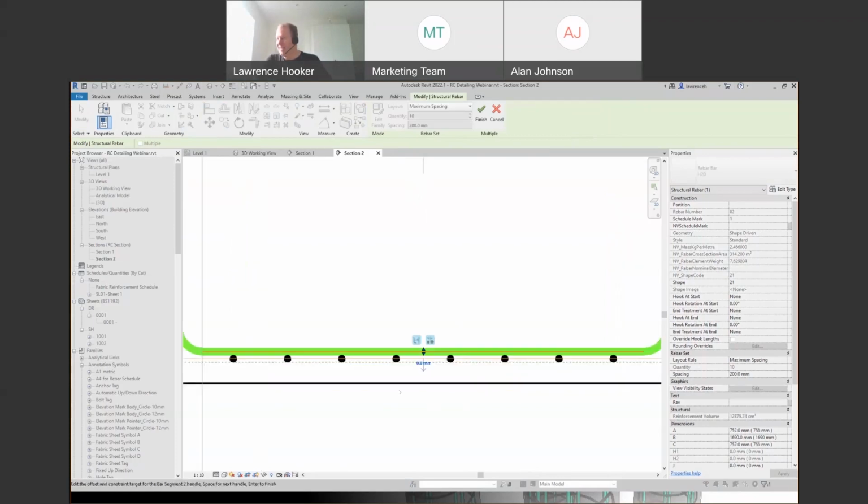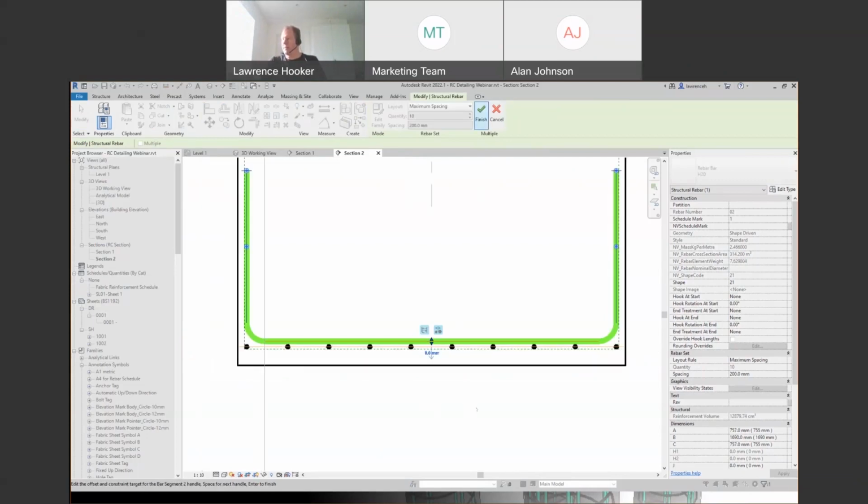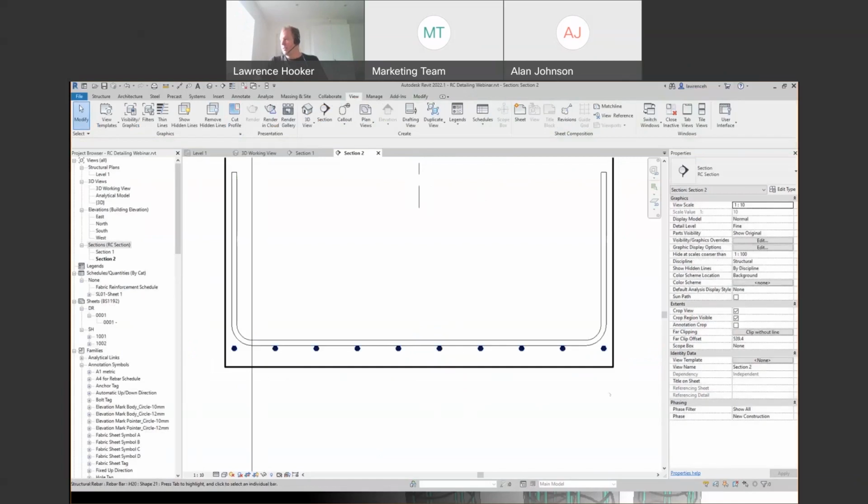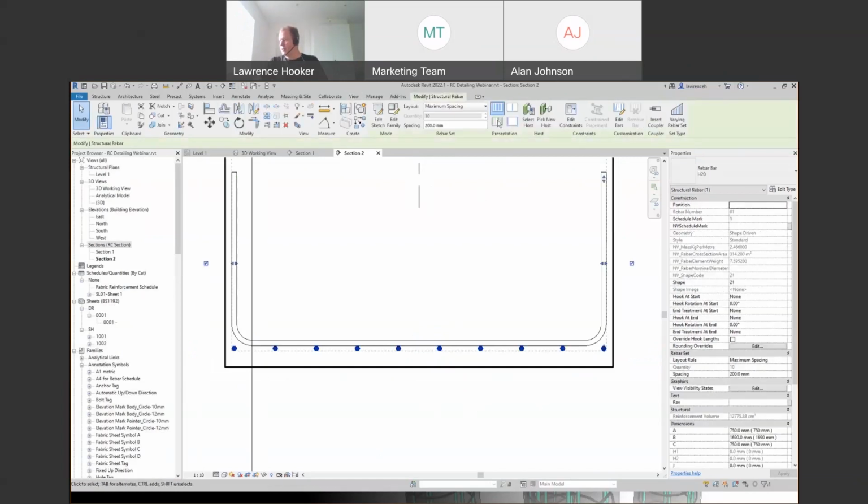And you can now see that it's constrained together. Now, what's quite clever with this is if I select this two-way constraint icon here, basically now I can change the B1 layer or the B2 layer, and that will then have a knock-on effect to the other layers. So it's bidirectionally parametric, which is really useful. Then I just click on Finish, and that reinforcement constraint is now applied. So I need to actually make sure that these ones are set to 750 as well.